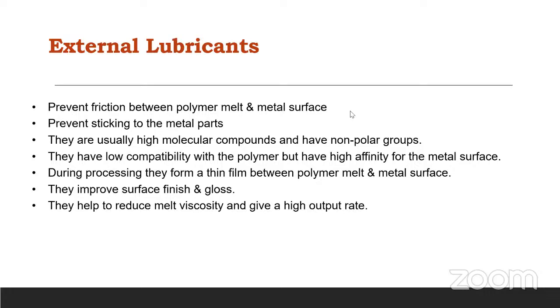Now, let me give you an example of PVC material. As I mentioned, the plasticizer is a physical interaction. In polyvinyl chloride, to process it smoothly, we add a plasticizer called dioctyl phthalate. PVC is available in powder form, and the plasticizer is generally available in liquid form.